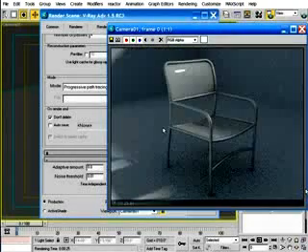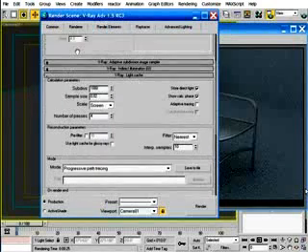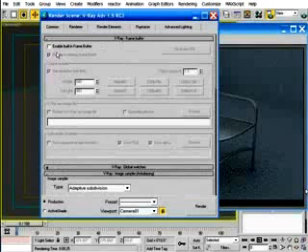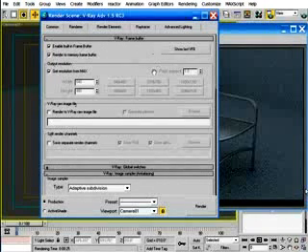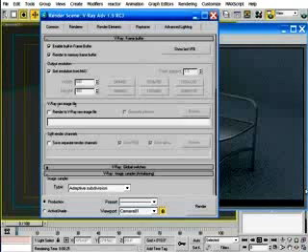the render window. Doing so can also result in VRay crashing or freezing up. So instead of using the 3ds Max frame buffer, try using the VRay frame buffer instead. You won't have the same problem with the VRay frame buffer. And this brings us to the next feature I want to talk about, the VRay frame buffer.